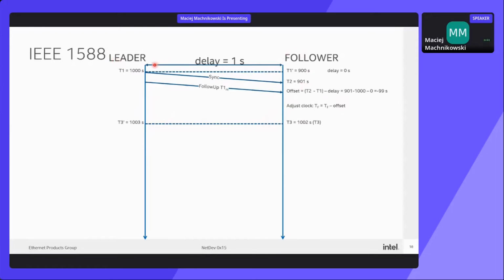And now, obviously, some time will pass there. We don't yet know what the delay of the path is, so we can only compensate for the difference of the clocks. So at this stage, the T3 will be at this value, and we will then send the delay request from the follower to the leader.